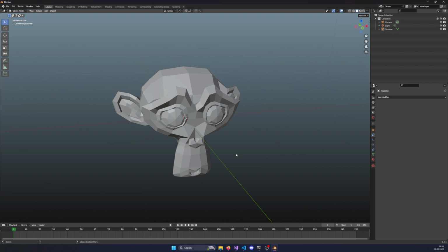And since we have the 4 vertices and 1 quad face, we can always convert this to triangles without issues. If we do it in Blender, it might even give us more issues, because Blender tries to be smart and maybe tries to interpolate some properties, or does not duplicate the properties, maybe applies some smoothing if it's a curve, and there might be things happening that we don't want.